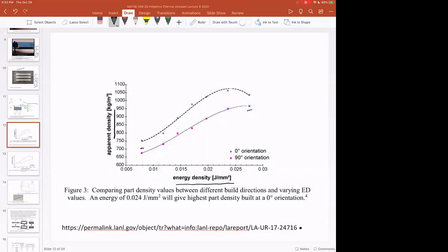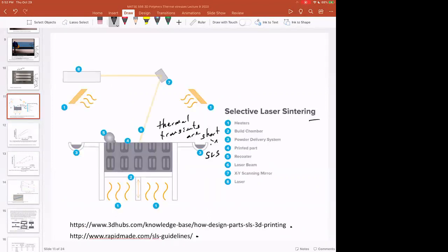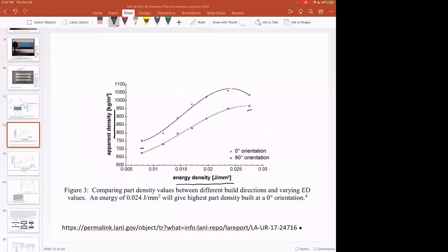Depending on the orientation of the part, it changes a little bit. But imagine, and this is not a perfect example, we're densifying a tensile bar on the surface of this bed, and we densify this part of the tensile bar a lot, and don't densify this part as much. Now you have a porosity gradient, or a density gradient, and that can cause curling and built-in stresses in the part.